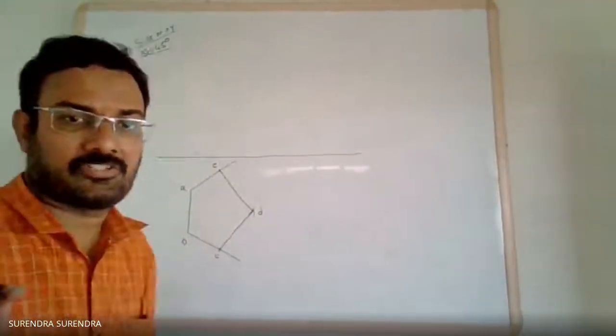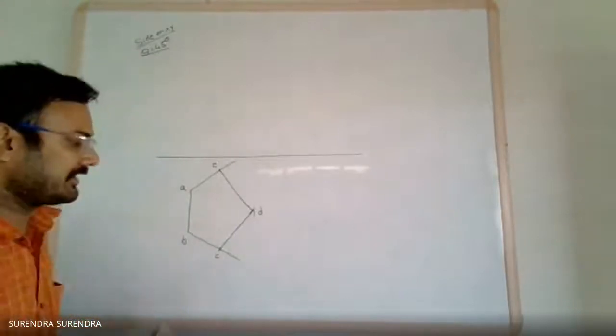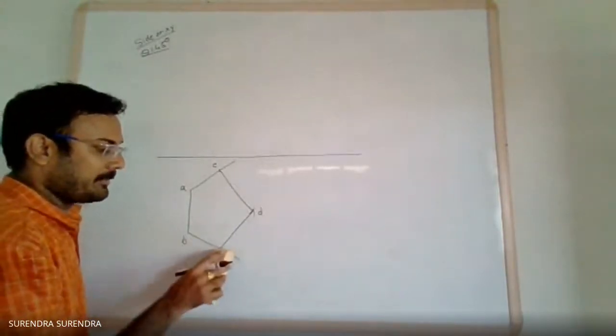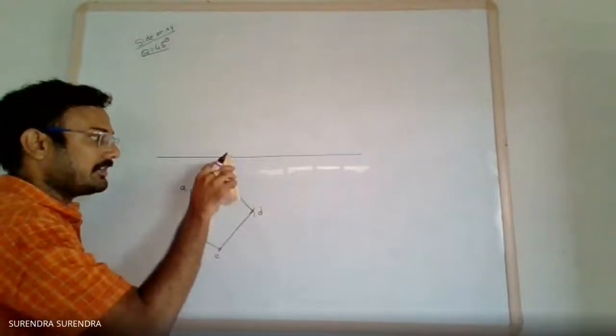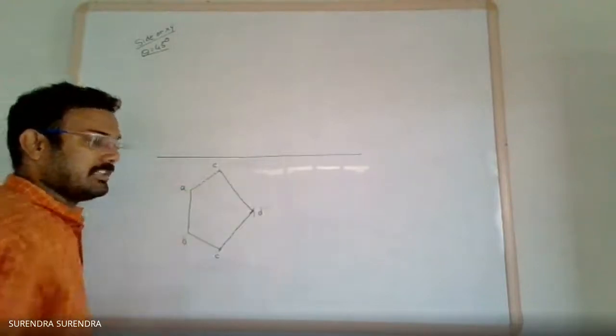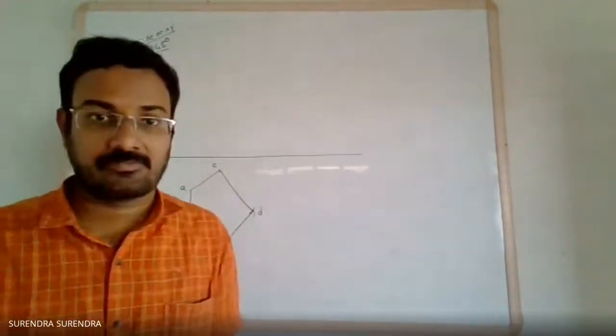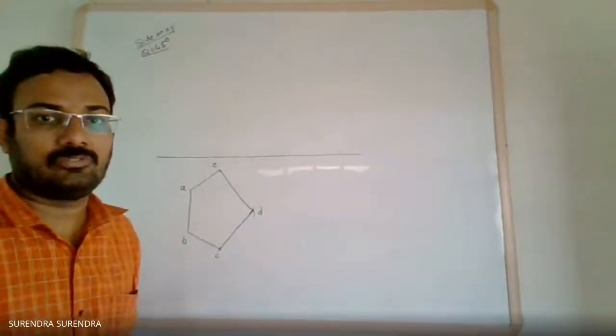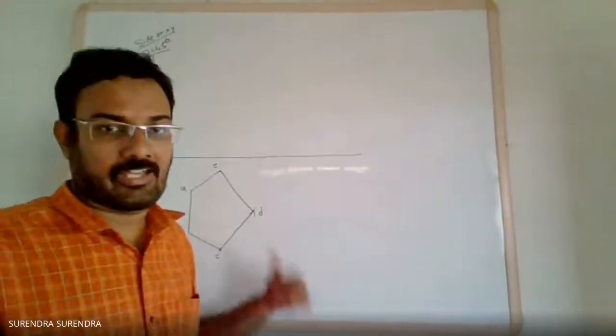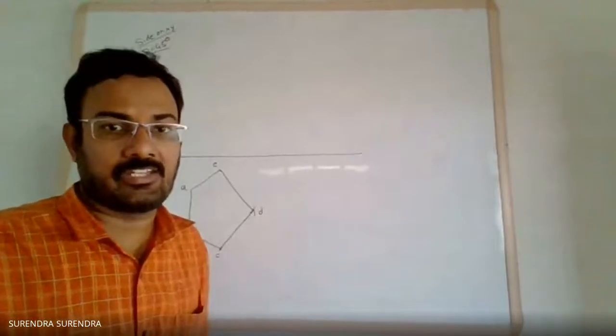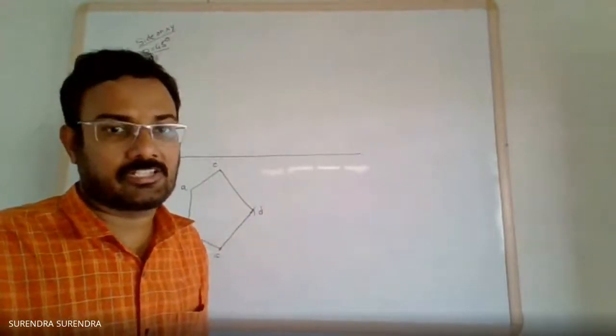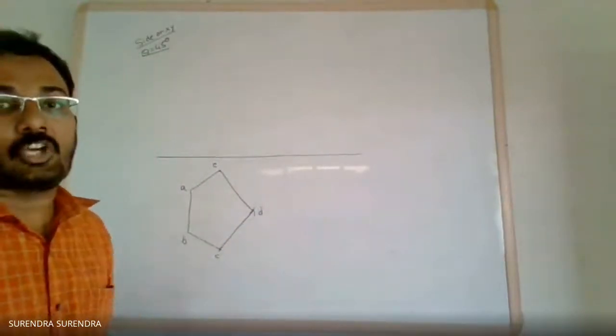So first initially draw everything with 2H pencil and then only highlight the polygon, and leave the remaining with 2H. Erase nothing, leave it with 2H. But as here it is possible, I am erasing it on board for clarity purpose. So with this, top view completed.